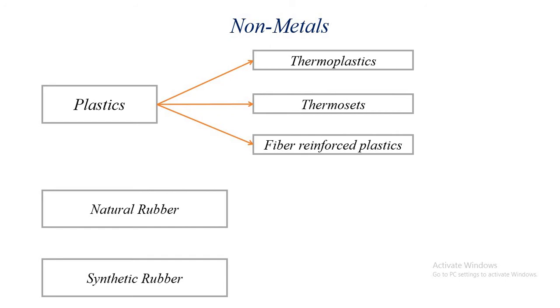Natural rubber. It is a low cost elastomer. Natural rubber is found in hard and semi-hard condition and it is used for belts, bushes, flexible tubes and vibration mounts. It is also used for production of coatings, protective films and adhesives. Rubber coatings provide protection in a chemical environment.